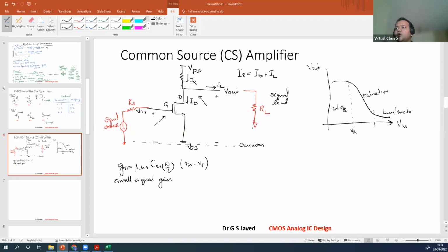Now, what is the output that you will see? The output that you see is multiplied by this resistor here. So the gain is given as, because of the internal gain, right? You see, this is the small signal gain. If you recollect, at this drain node, the resistor is connected to ground in the small signal part after gm VGS. So the Av will be gm RD. And if you remember, the sign is going to be negative. There is an inversion that is happening. So gain is going to be minus gm RD.